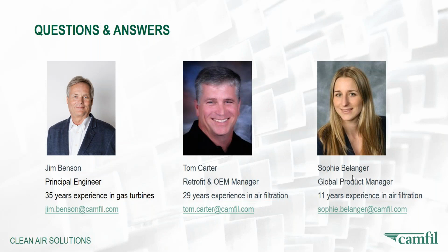Okay, I guess I can take that one. So in addition to pressure drop, as filters get older, what we like to do is have filters returned to our engineering test lab for evaluation. We'll validate the pressure drop that's being reported by the site, and 99% of the time that always agrees. And then we'll measure its efficiency to validate it's still performing at the level it needs to, from that perspective of keeping the particulate out.